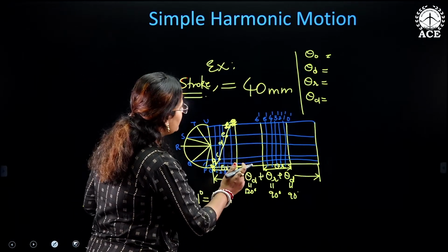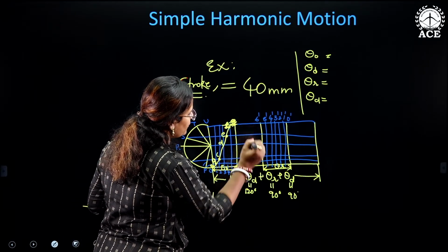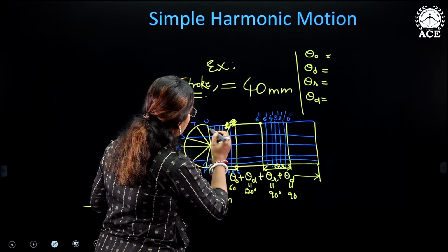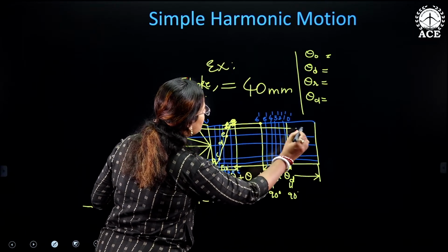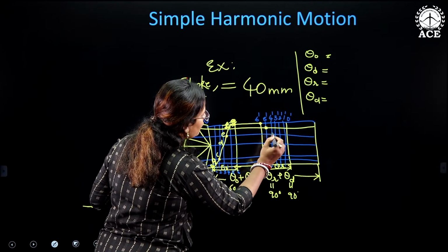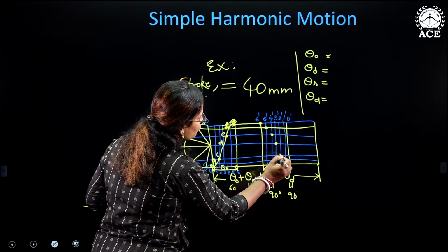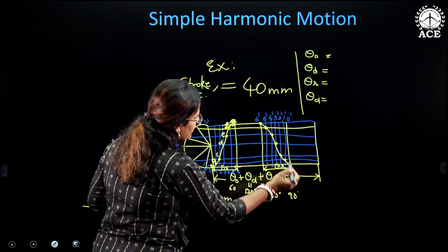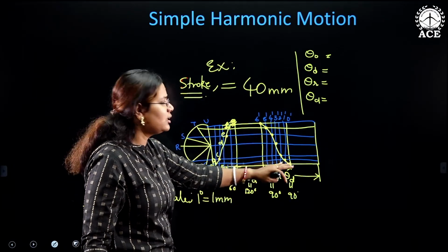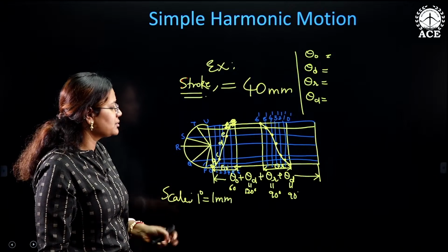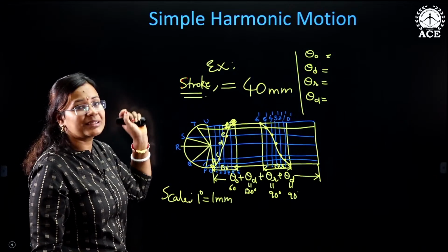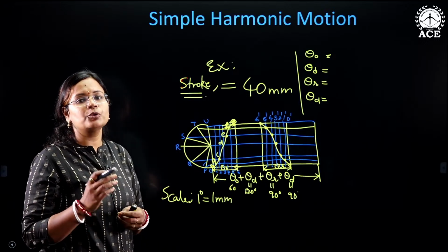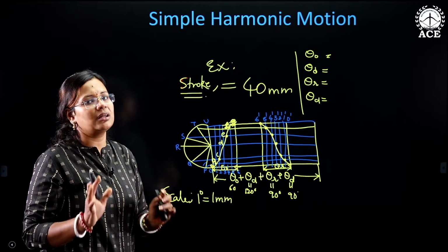Same thing we will do here, or we will point out here also. Let us say it will follow on the sixth line over here, and then the fifth line over here, 4, 3, 2, 1 and 0. So if you trace this curve like this, it is going to generate a curve path. Okay, so this is nothing but the method of drawing a displacement diagram whenever the condition of the motion of the follower is given to be simple harmonic motion.